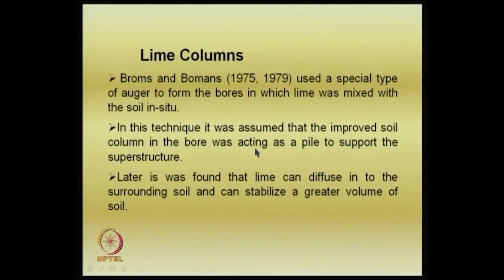This is another method. You have a number of methods to improve the bearing capacity and reduce the settlement. In this technique, we assume that the improved soil column in the bore is acting as a pile to support the superstructure. Later, people found that the shear strength of the soil in the clay is so low, but when you treat the lime column, that material has a zone of influence around it, and it is definitely a much stronger material. So one can treat that as a pile.